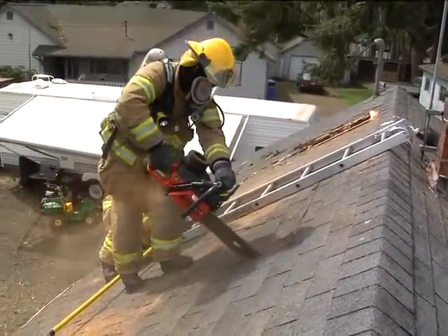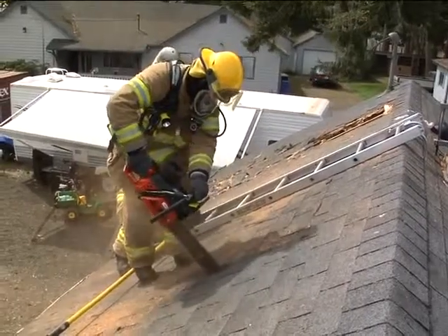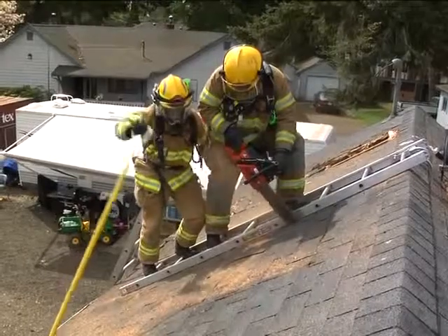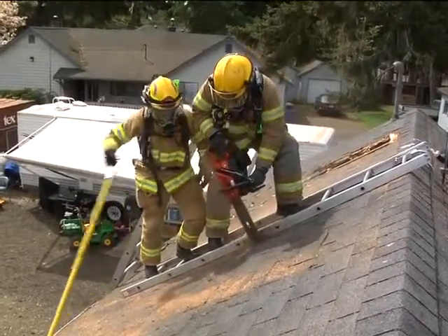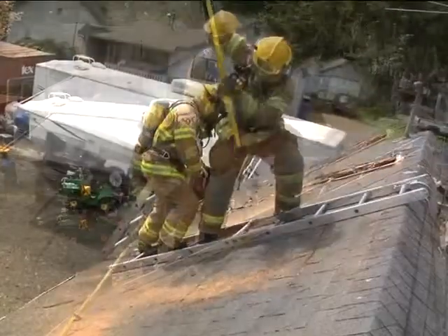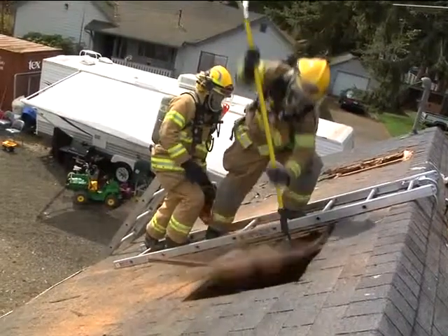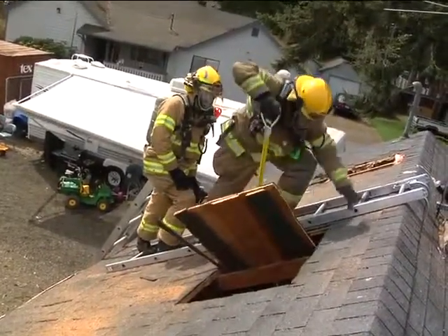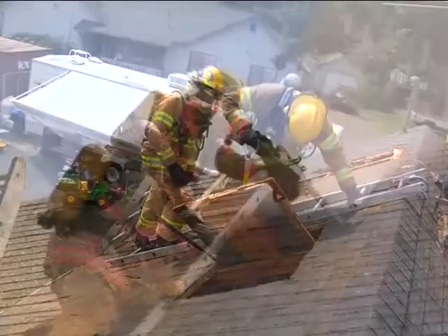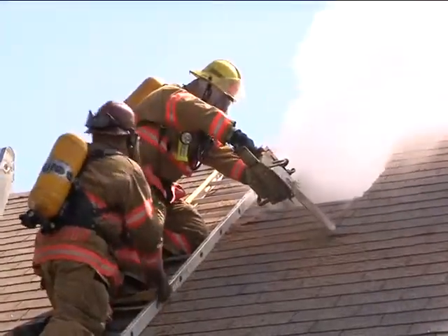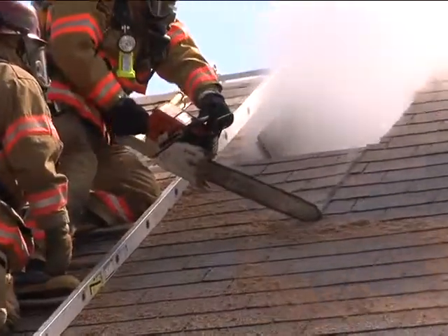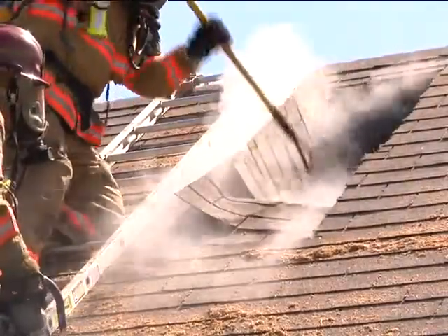Make 2 parallel cuts to the roof supports and between pairs of joists to form a rectangle. Strike the nearest side of each section of the roof to tip it in, using the middle support as leverage. By continuing this cutting pattern in any direction, you can rapidly open a large section of the roof.